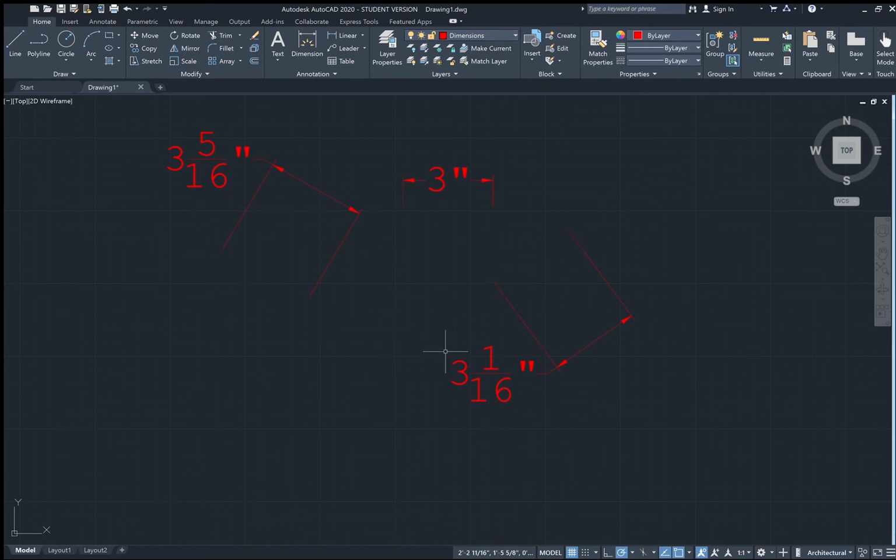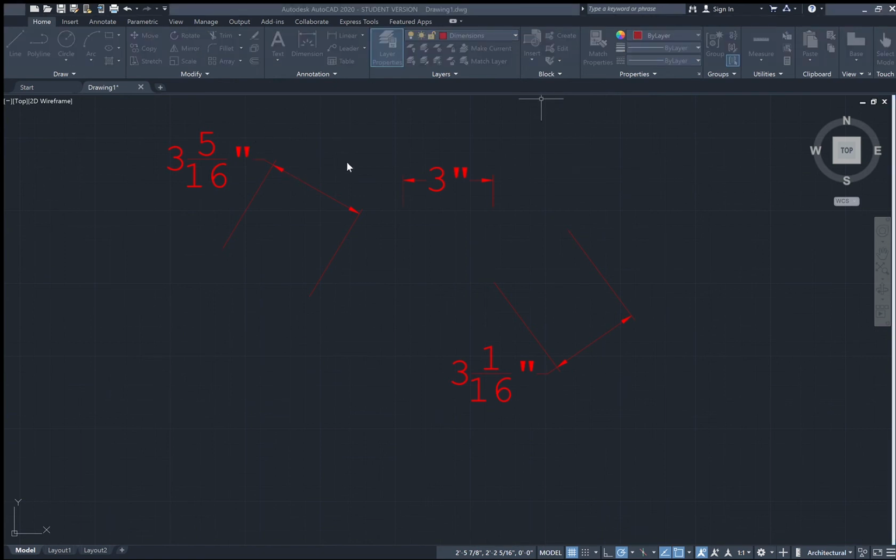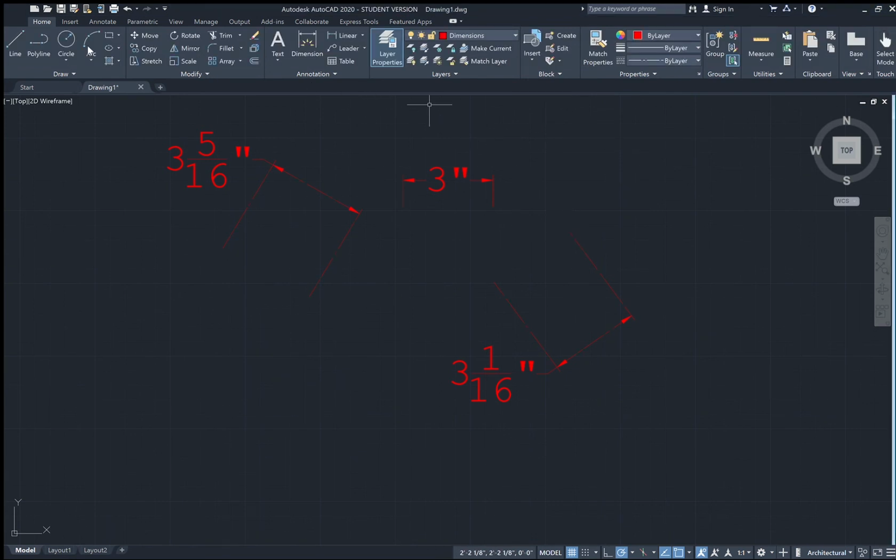Only the dimensions would show, which is important. And obviously, if you were wanting to change anything, you can go into the layer properties. We can say the line type we want is center 2 for dimensions, the dashed line. Now when we close out, all of our dimensions on the dimensions layer are now perfectly dashed lines.